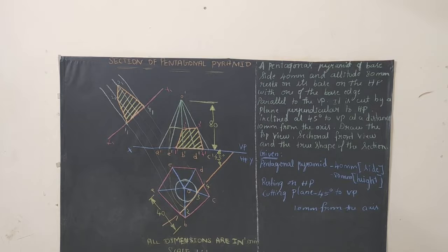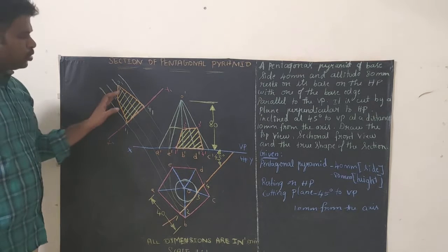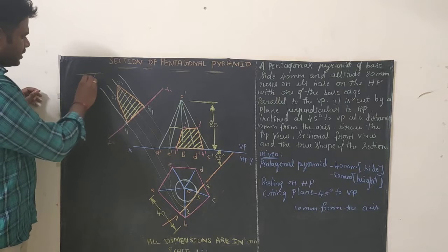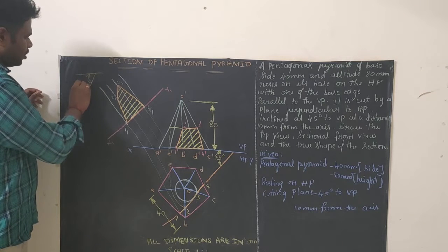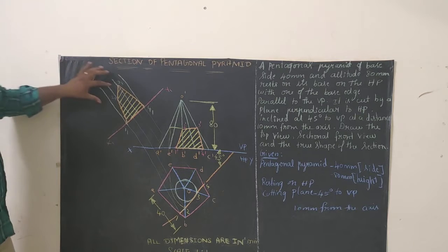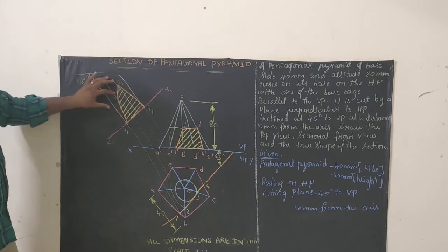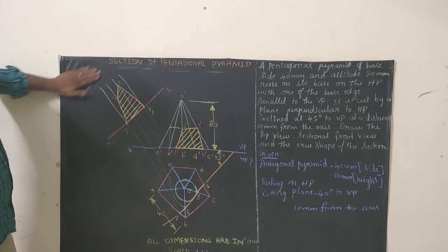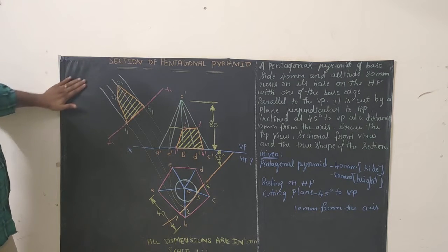So last step is hatching alone. So you know how to draw hatching. Hatching 45 degree. Draw a reference line like this. Take a reference line and for 45 degree, draw a line like this. Then you can draw hatching with respect to this line. So hatching should be done with 45 degree angle and equal spacing. After that you can rub it off. Okay, it's for your reference.